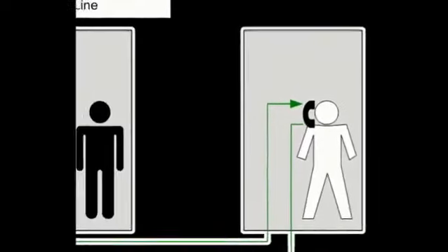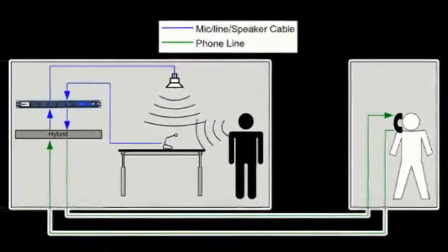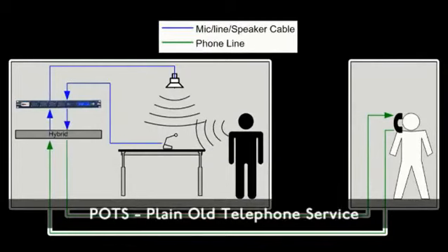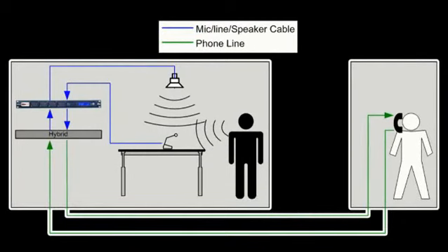The two sides will most commonly communicate over a standard POTS line, although the use of full bandwidth T3 line is not unheard of for communication over short distances. The fundamental problem with this setup is that it causes the far side talker to hear echo added to his or her voice. There are two different reasons for this.